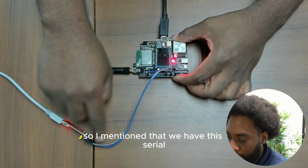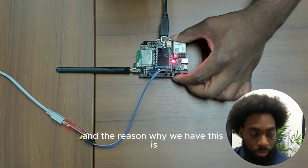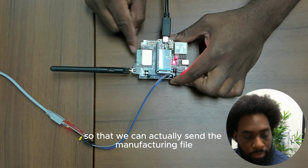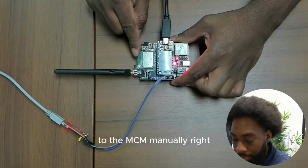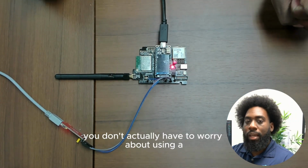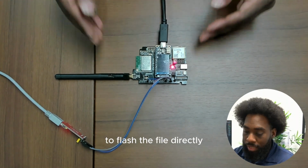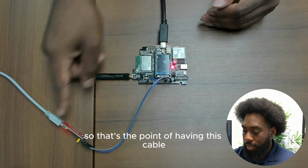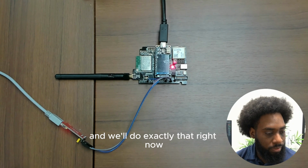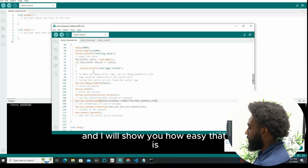So I mentioned that we have this serial to USB interface, and the reason why we have this is so that we can actually send the manufacturing file to the MCM manually, right? So you don't actually have to worry about using a debugger probe or anything like that to flash the file directly. You can actually just pass it serially. So that's the point of having this cable, and we'll do exactly that right now. And we'll show you how easy that is.